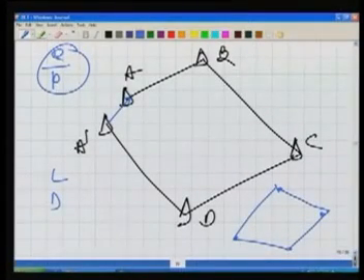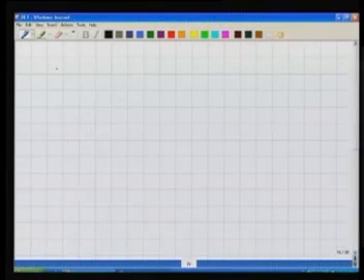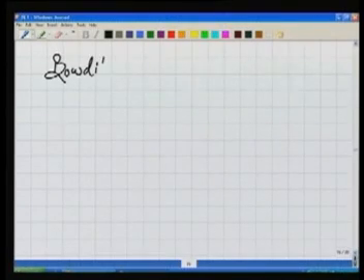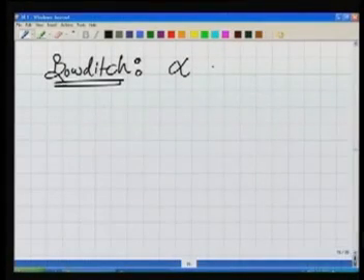Again, we'll go back to the compass. In the case of the compass, we had applied the corrections and we moved each point in such a way that we found a new traverse which was the closed traverse. And we know how to apply the corrections. We had closed the traverse. What we will do now, we'll apply the corrections again in a similar way. The first method of applying the correction is Bowditch's method. This is the same method as we used in the case of the compass. In the case of the compass, we discussed only the graphical method. Here we can apply the corrections mathematically by some computations. How do we apply the corrections in Bowditch's method? Here the assumption is the corrections are proportional to the length of the line.